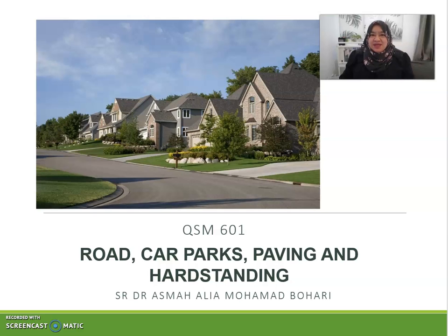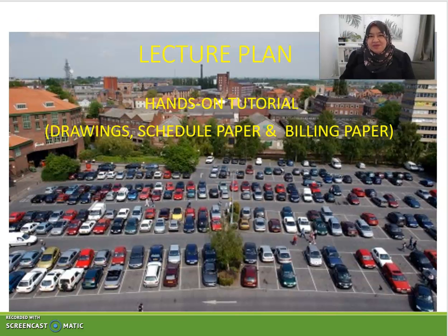And for this week, we will be looking at the topic for the road, car parks, pavement, and hard standing measurement, and taking off and or producing of the BQ for these particular elements. So I hope all of the students are ready with your necessary drawings that have been provided to you in the Google Classroom, and the schedule papers, billing papers, calculator, and also the standard method of measurement. It is a must have reference whenever we do a taking off for building works.